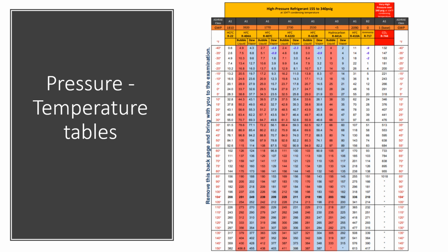As a slight example, just to make this easier, if you are working on an evaporator and you're taking the temperature reading on that line, and it says 45 degrees, that means that the pressure right there where you're taking the temperature is going to be 76.1 psi. You don't even have to have gauges hooked up to it to know that. All right. Now, we'll discuss a little bit more saturation temperatures, and we'll talk about superheat and subcooling and how that affects a system in a few slides.